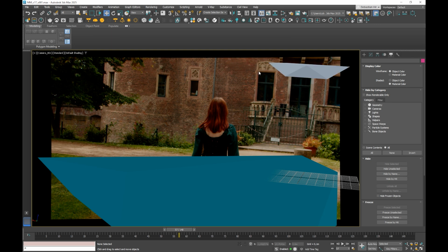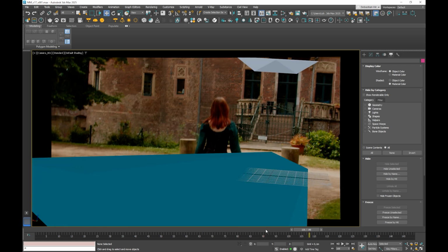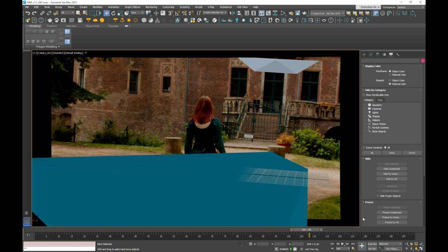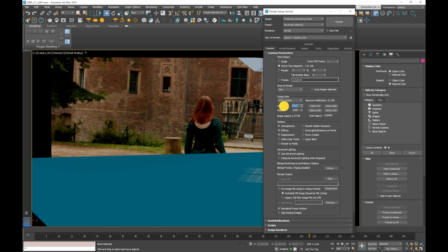So this should actually align with the window here. It doesn't anymore. So we have to change the camera, and there's different ways how you can do that. First of all, you can check what resolution you have rendered out of Blender, which is not the full HD resolution, but 15% more.